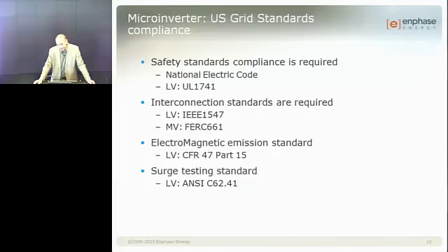Funny enough, there's an interesting anecdote on this. The reason this test stops at 6,000 volts is because it's actually a very old standard, and they did a whole bunch of surveys in houses and industrial locations and all that. And what they found is that when the voltage exceeds 6,000 volts, all the outlets start arcing. So there's no point in going higher than that because it's self-limiting, basically. So our box can take that and no more.